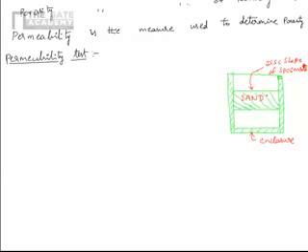Suppose for example you are preparing a mold with a particular sand. First you take that particular sand and prepare the circular disc and keep that circular disc in this specimen, and allow the gases present in the bottom of the sand to go outside, because of pressure difference it will go out. So we have to measure the time taken for the gases to come out. So that is what permeability number is, a function of time.